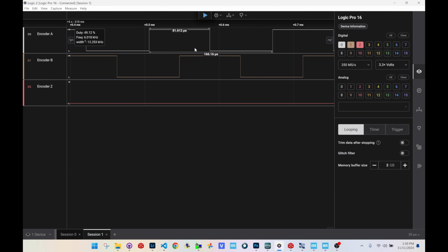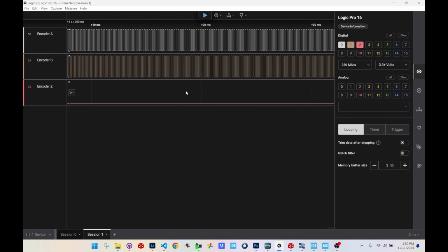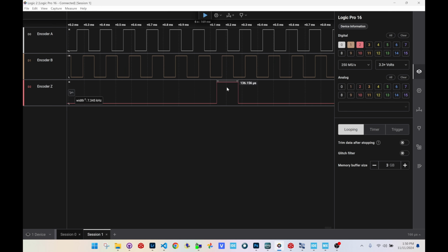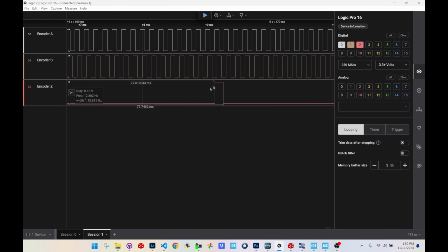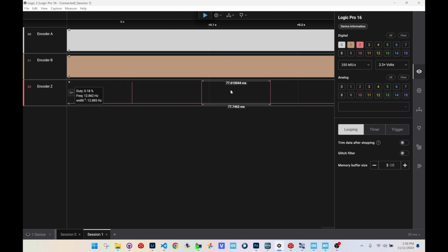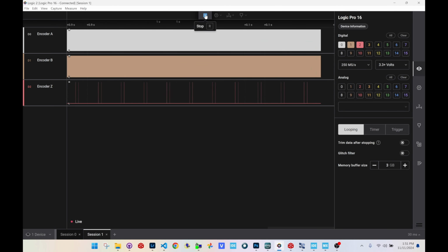In order to commutate the motor, you must know the rotor position. Luckily, this motor comes with an encoder built in, so we don't have to do a sensorless algorithm. Timer 2 is set in encoder mode, and encoder sides A and B are fed to this timer. When the encoder moves, the waveform is used to count the timer up and down. I use the 0 pulse of the encoder in order to zero out the count register. This fixes the problem of encoder drift and synchronizes the encoder to the rotor.